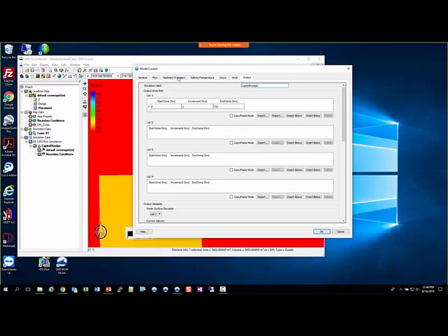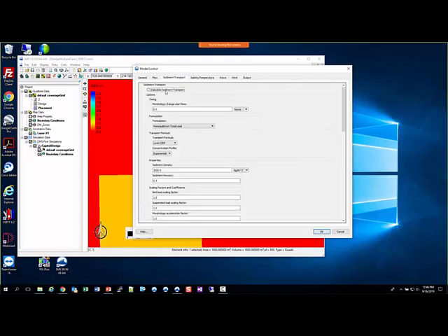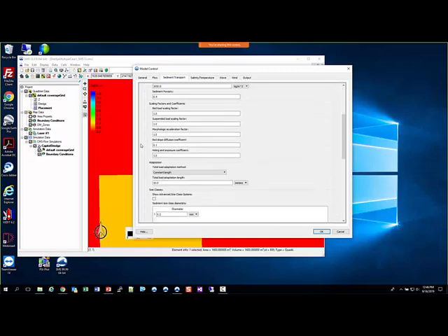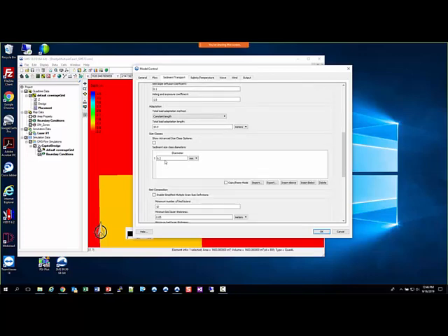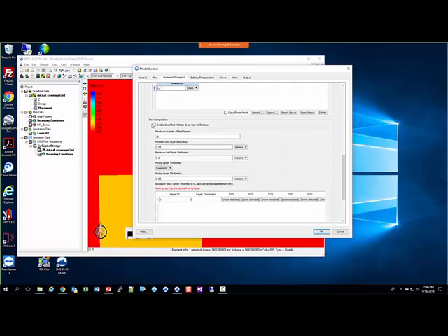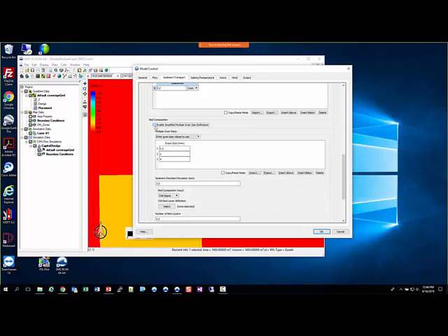So we go to Sediment Transport, and I'm going to turn that on and then make a couple of changes here. So we're going to go with a size class of 0.2 millimeters. And then for this case, we're enabling the simplified multiple grain size definitions. And I evidently had already had this set up. But when you would come in here by default, these would be empty. You would insert rows for the ones you want. And then I'm adding the values for the grain size as I specified in the notes.